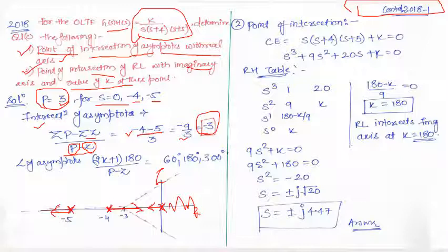Now we need to know that when these 2 root locus branches coincide, how they will move. Okay, which ones? The one starting from the origin and the one starting from -4, because obviously they are moving towards each other, hence they must coincide somewhere and then go somewhere else, and how they will move will be decided by the asymptotes. Okay, and obviously the asymptotes also intersect at the real axis, and that point is being asked in the question, which is -3.